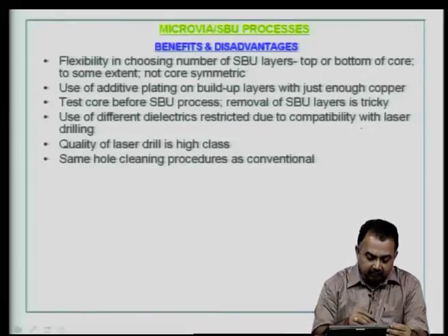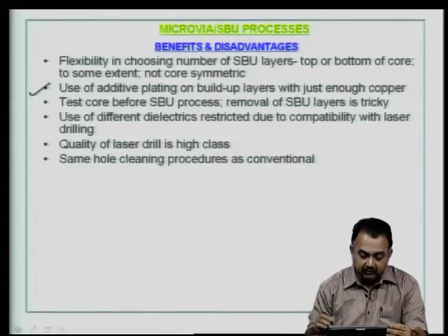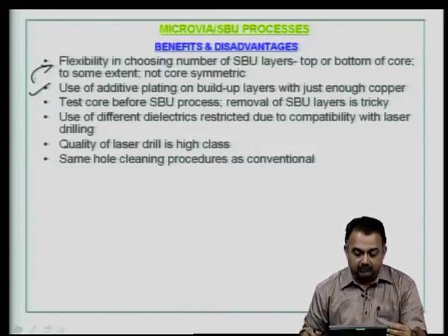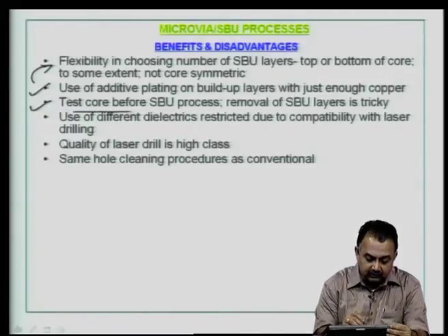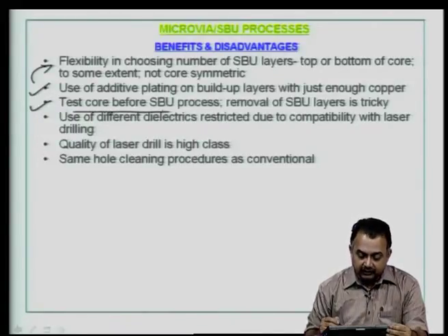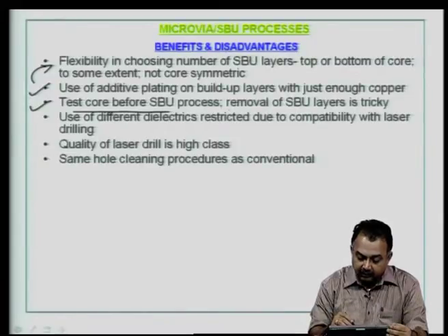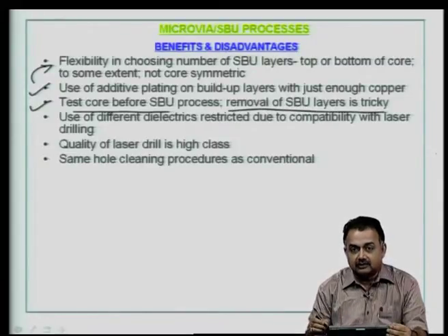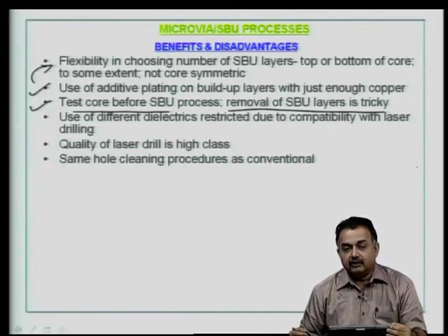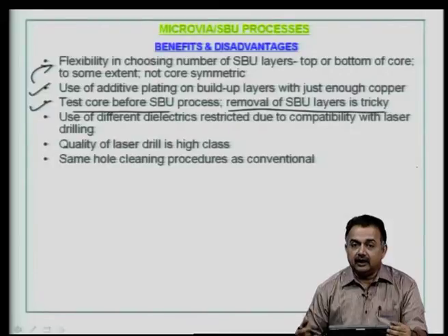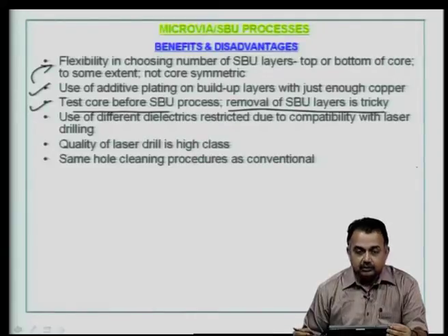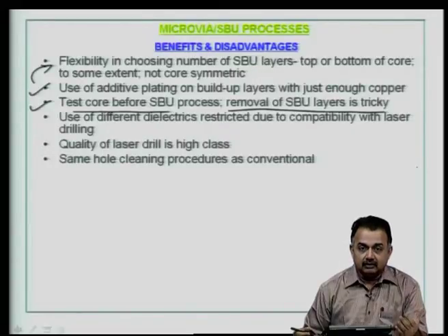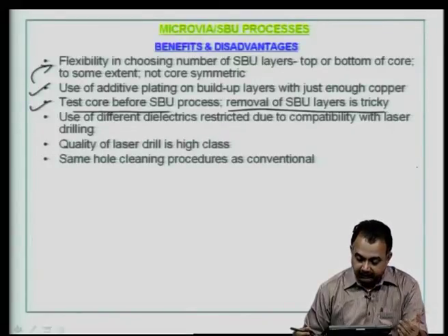and that will not add to the issue of warpage. Use of additive plating on build-up layers with just enough copper will enable this kind of problem to be solved. Test the core before the SBU process. So, once you prepare the core, you need to test it, because the removal of SBU layers is still a tricky process. Although before the curing process you still can remove the dielectric ink, after it is cured it is still going to be an issue to repair the SBU layers. SBU here refers to sequential build-up layers or built-up layers.